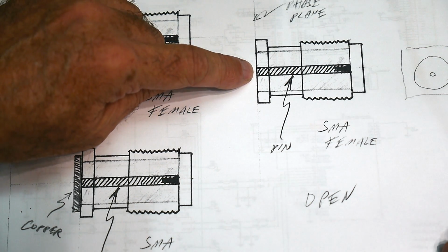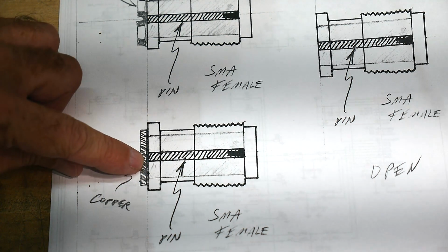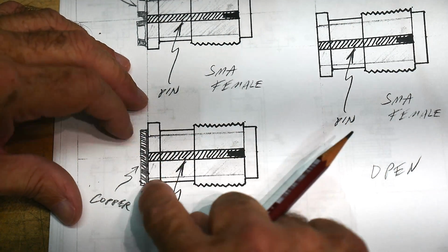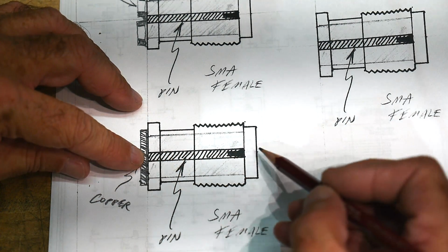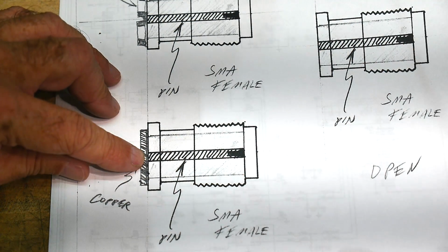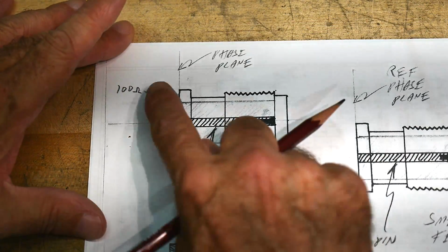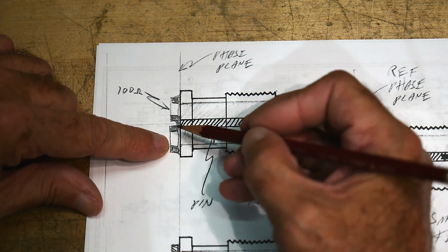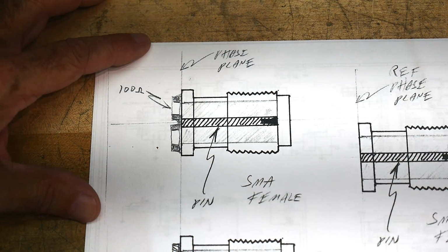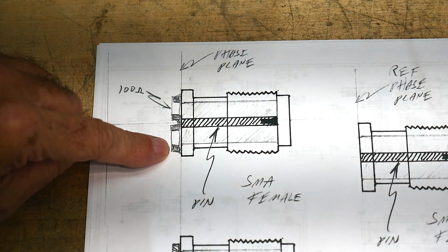Okay, so now we want to make a short. We want to make a cal short. The cal short has to have the exact same reference plane. All right, so there's a little piece of copper put here, and it was soldered in place, so now everything's shorted together, and when the electrical signal comes down, it sees the short and it reflects back out of phase. But where does it reflect? Right at this plane, at the reference plane. And then putting in two 100 ohm resistors, I tried to keep them exactly on the reference plane. I'll let you think about whether it's important to preserve the reference plane in the load or not.